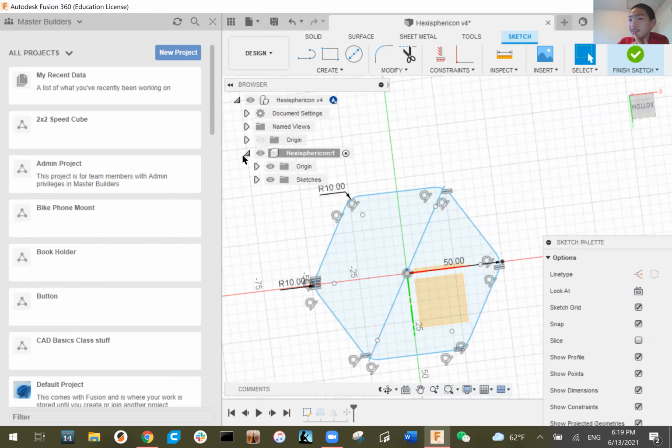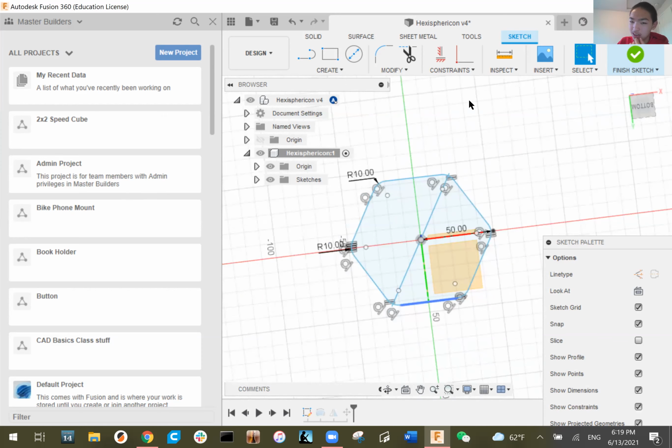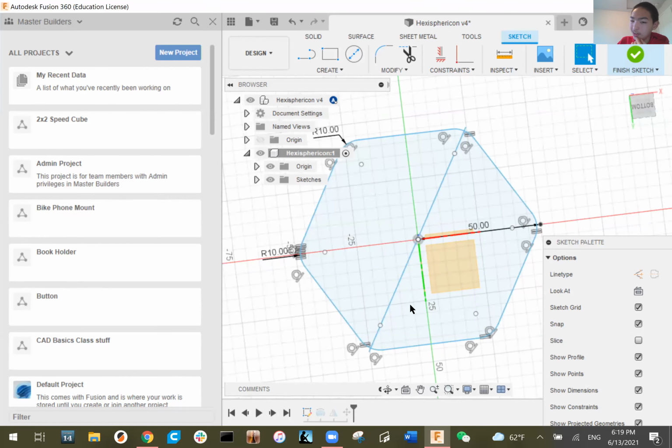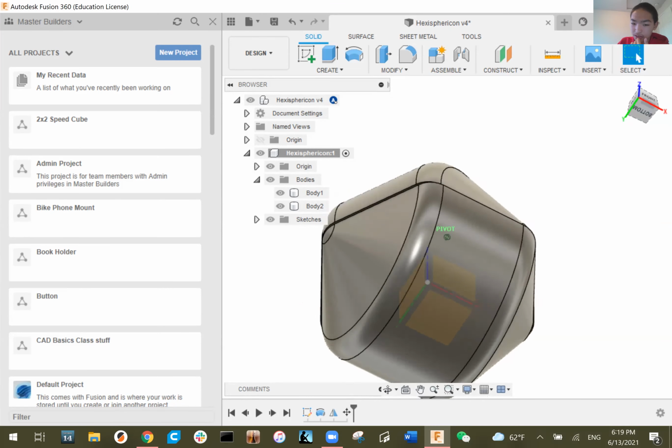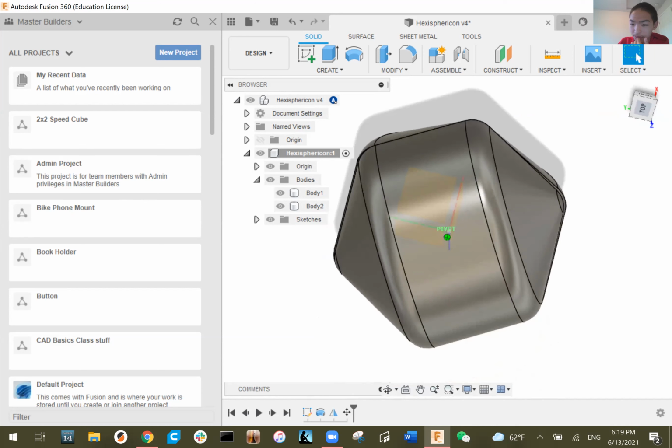All right, if you guys weren't able to follow along with the revolve and everything else we did at the start, just start from where we are right now. Draw a hexagon, and then draw a line from corner to corner, and then just round off all the corners on the hexagon. And then just follow along with what I do, because if we just do the rounded corners, we just have two hexagons with round corners.